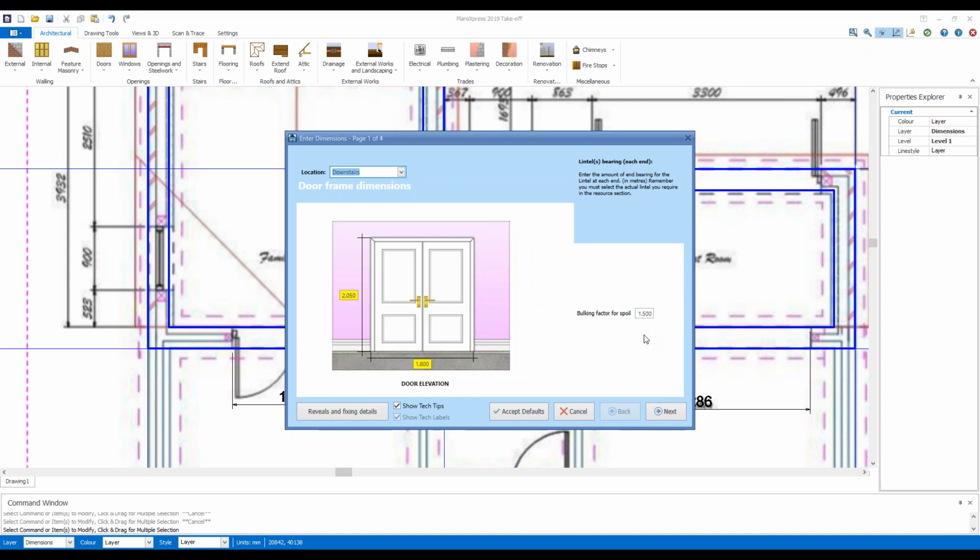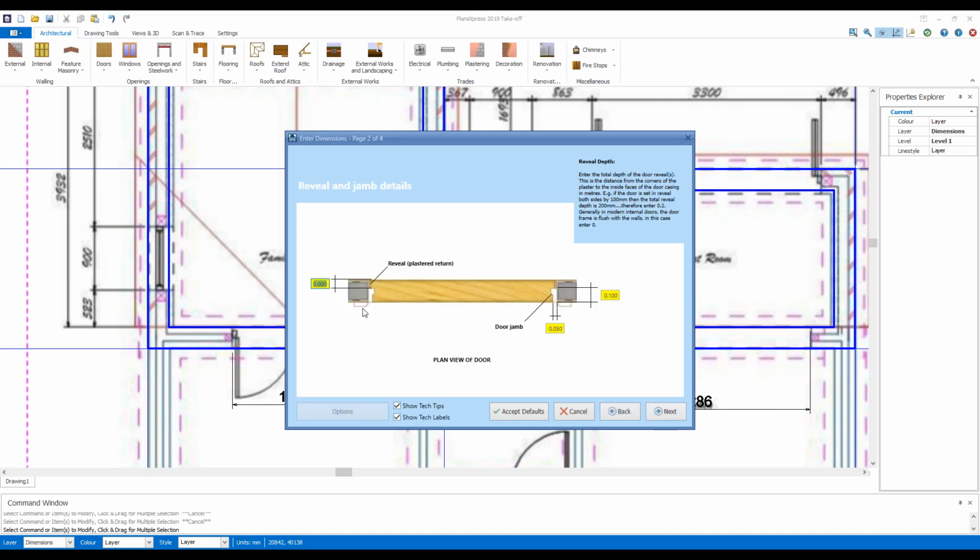So when you take things out of a wall, it might not necessarily be the same shape as it was when it was in the wall, and it might bulk out for things like skips, so skip collections, that kind of stuff. So yeah, just make sure you put a bulking factor in. If it's block work, I'd probably put 2. But if it was ground, I would probably put 1.5 or keep it as default.